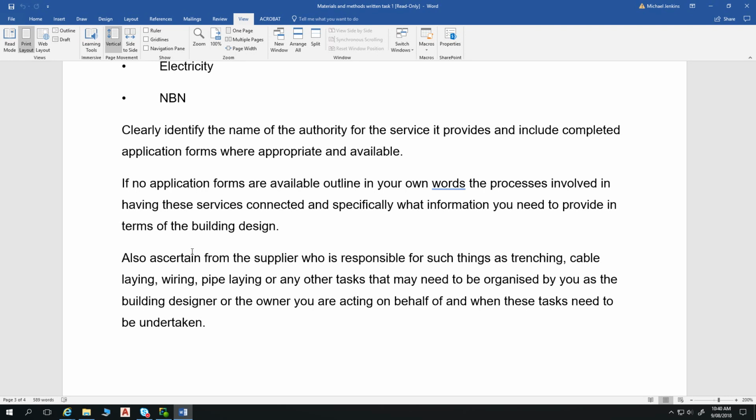Some places will be restricted to just single phase 240 volt power. Other places will have options for more. And it's important to understand that because some of the appliances that you run in your house, like giant air conditioning, although I hope you guys are predominantly smarter than designing around relying on massive air conditioners, you've got giant air conditioners that run off three-phase power that will require that 415 volt supply. It's important to understand what is available at your site as well.